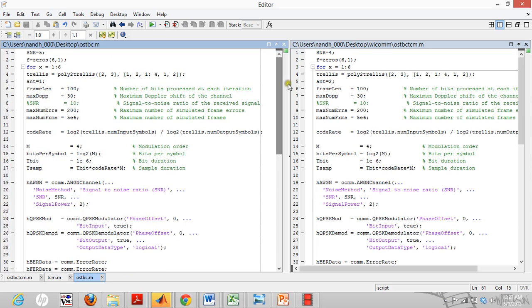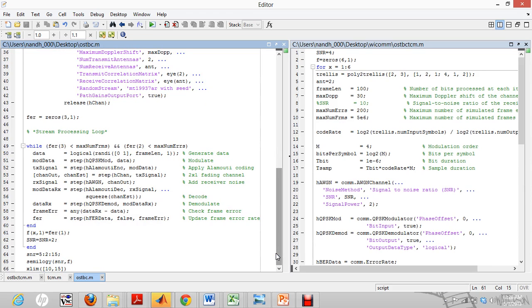As you have seen, I initialized the number of antennas on the transmitter side as a variable, AT. This variable AT basically proves that I can keep changing the antenna numbers, and I got different values and plotted them. While in the OSTBC TCM, it would use both a PSK TCM modulator and an Alamouti encoder, and the same demodulators for both. Here they use an AWGN channel.